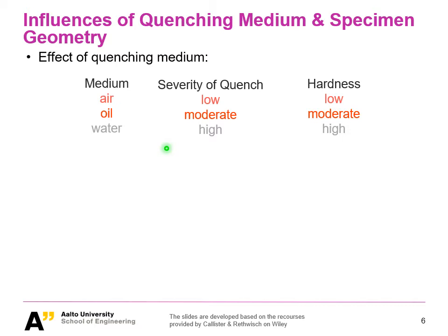You have learned already the first one, which is furnace cooling, right? This is cooling of your material together with the furnace. That is not so much used except for full annealing, of course. But you can imagine that is rather slow. If we don't have specific requests, we would rather go to other conditions, especially for quenching.